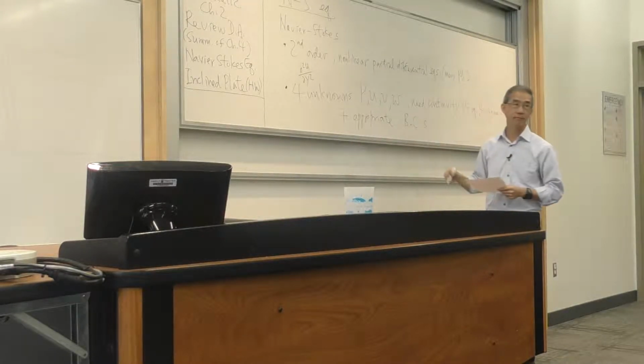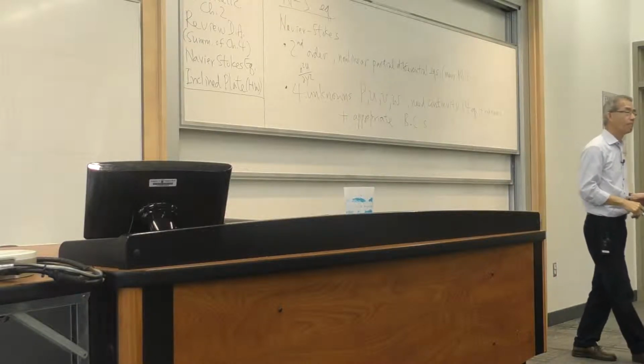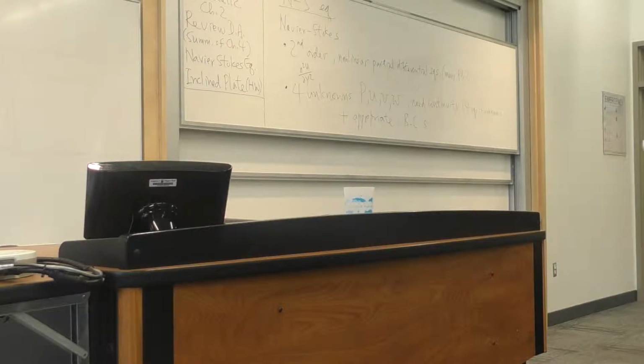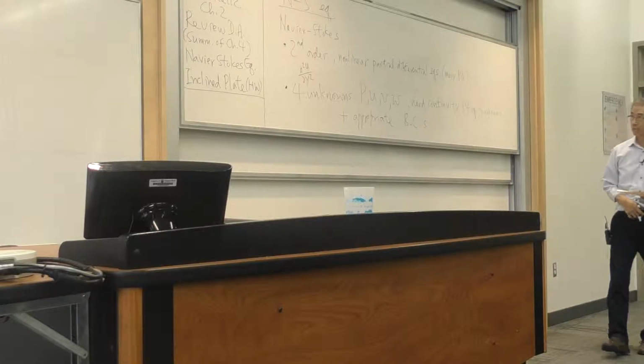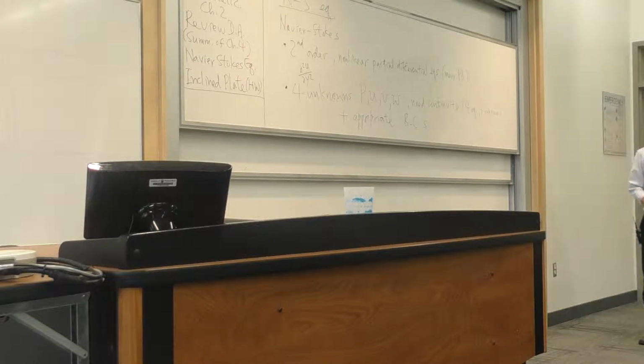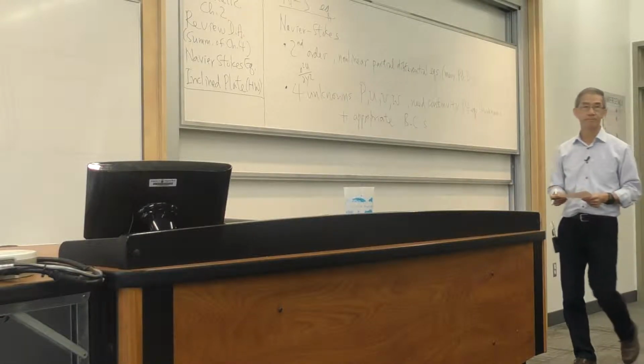What's BC stand for? Boundary conditions. First, give me a domain, a geometry. You're solving a problem in the combustor can, and then you set up a mesh or grid, and then you apply this equation of continuity and Navier-Stokes. You get all that solved. At the edge of the domain, at the boundary, you have to impose the condition appropriate to your problem.